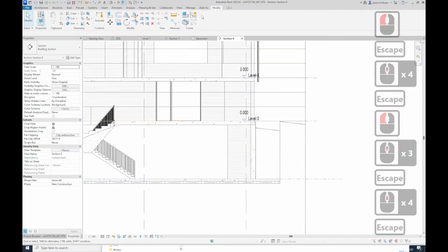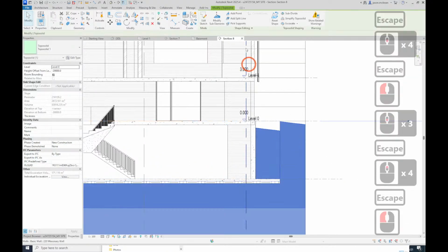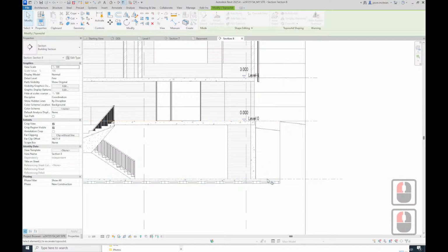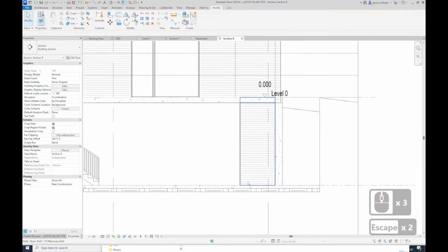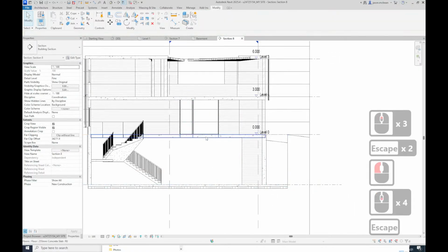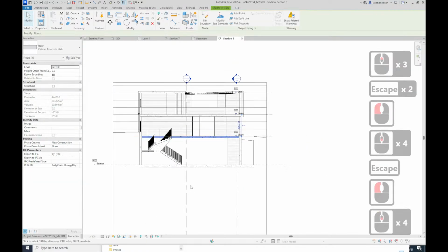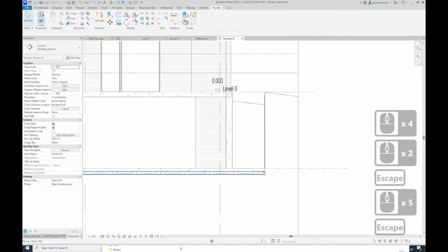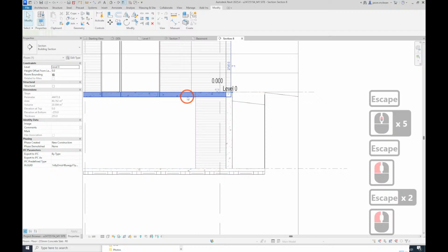Now, on topo, is that the 150 layer? That's 150, because when they compact the fill, it's in layers of 150 mil. Then they compact and then put another, but we represent it as 150. We don't show all the layers because we don't know. And the concrete slab above is fine, because it bears on ground. Okay, got it. These don't bear on ground. That makes sense. Okay, ground bearing, they're thinner. When they're suspended, they're thicker.